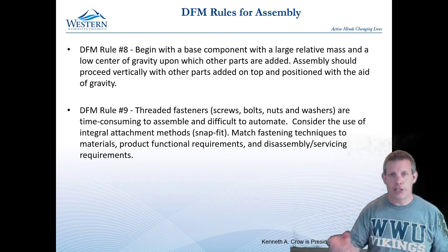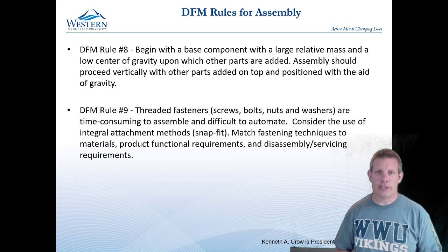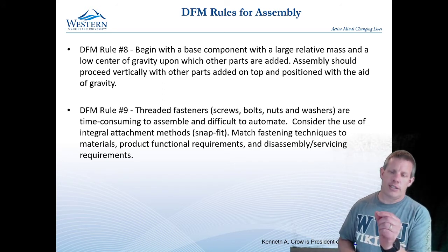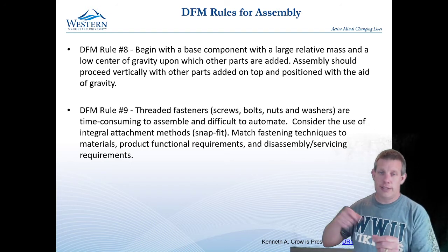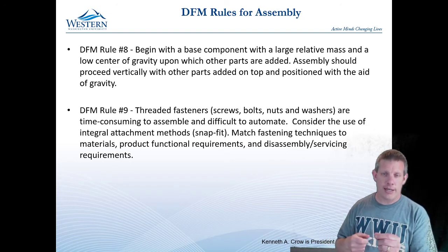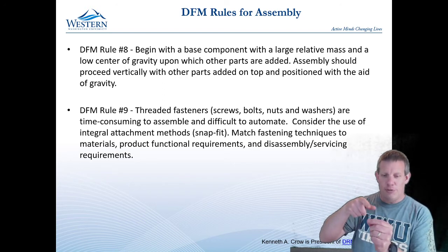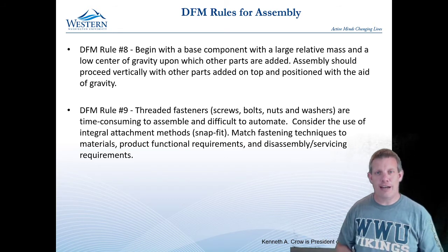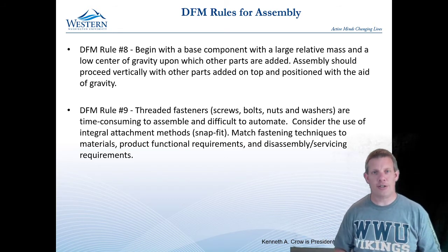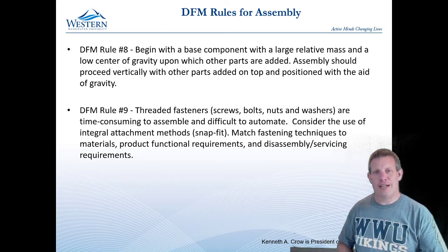For the initial assembly, it is absolutely true that screws are very slow, because to bring something together a small amount with a screw means that the screw has to rotate many, many times, and it typically has to rotate starting before it gets to the point where it's drawing the two together, and then it has to rotate afterwards.